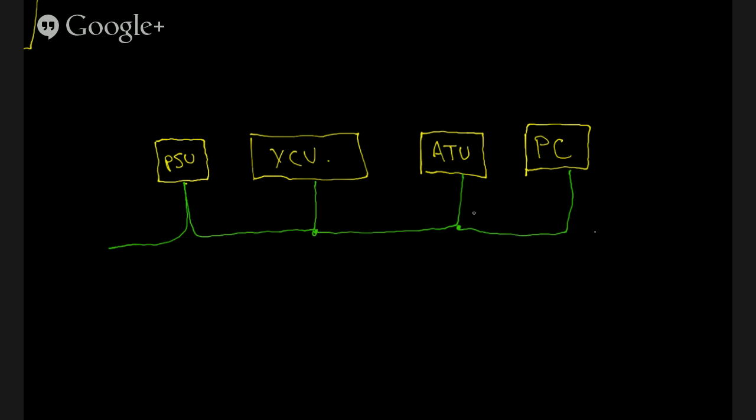And we run into issues when back current, which usually will come from our RF source here, ends up creating a path, for example, the ATU connected to the transceiver here. We can create a path for current to flow.